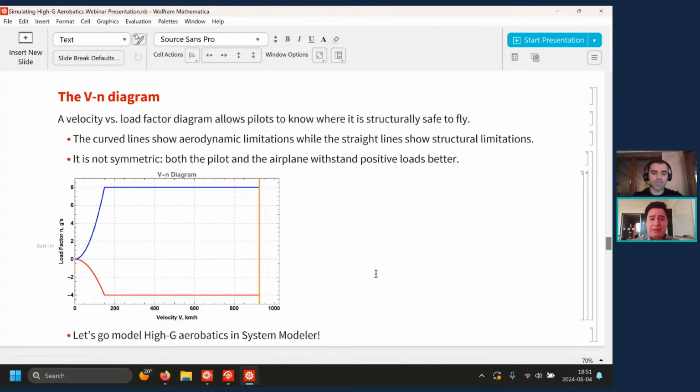In the military area, it might be a bit different. Maybe, as you said, the Swedish Air Force, for some reason, has the need of withstanding 12 Gs. That's the upper limit of the V-N diagram. So probably they will publish, we need a new fighter jet that withstands 12 positive Gs and -6. And then, of course, there's some kind of bidding and these really, really complex things going on. But then the designers will actually try to achieve this using structural design.